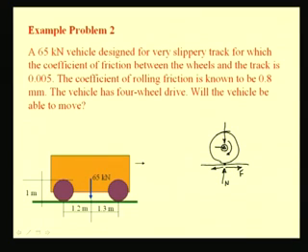and this developed force for traction should overcome the rolling resistance. So, we have to ultimately see that the rolling resistance has to be less than the maximum available friction on the track. If this condition is satisfied, the wheel will be able to propel forward.